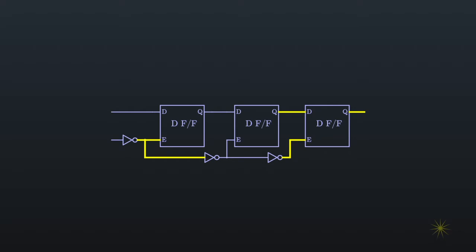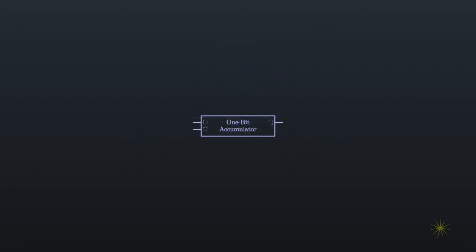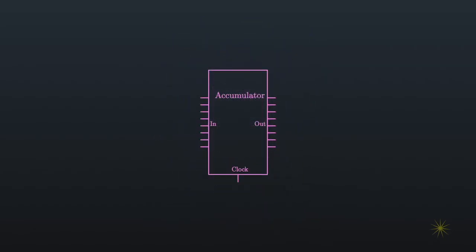This creates a new gate whose contents of the input line is stored when the clock signal rises, but the contents are not written to the output until the clock line drops again. We can encapsulate this collection of gates into a new 1-bit accumulator circuit, and this is our complete accumulator, capable of reading and writing a result all at the same time.